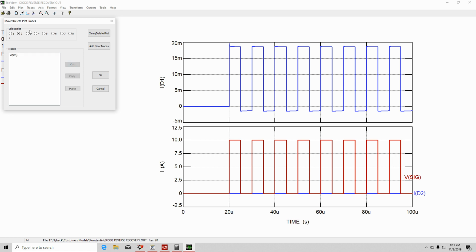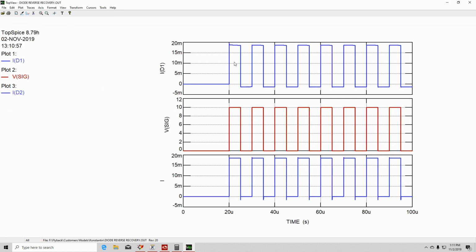This one we'll cut and we'll put it in the... Okay, so if you notice here, this is the 1N4004. It conducts, and then throughout the entire switching time or period, it's conducting the opposite. It never goes to 0. So what happens if you use this in a switching power supply? Your capacitor will never charge, because it'll be charging and then it'll be discharging.